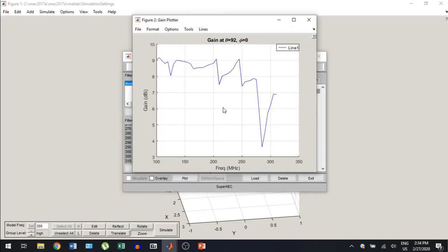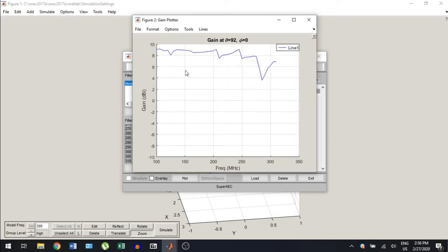And here we have the overview of our gain versus the frequencies we've simulated at. It looks a little choppy here, but if you just decrease the increments at which you're simulating, you should get a nicer version of it. We can also show a smoother version of this gain graph. If we go up here, go to axis limits, select manual, and change this Ymin and Ymax from -10 to 10, it should give us a better shape of the gain overall. And you'll see that's slightly smoother and a bit more what we expect.